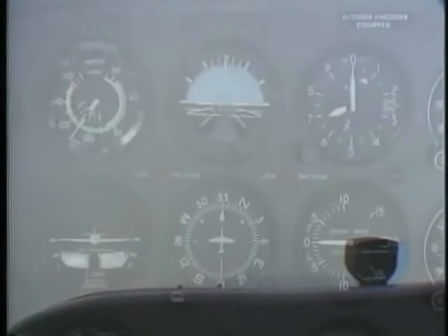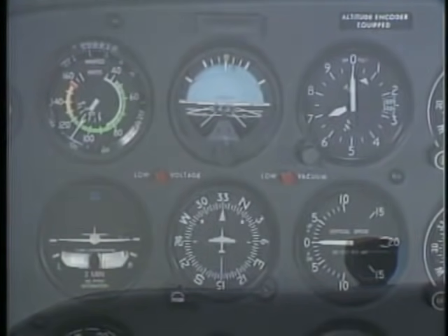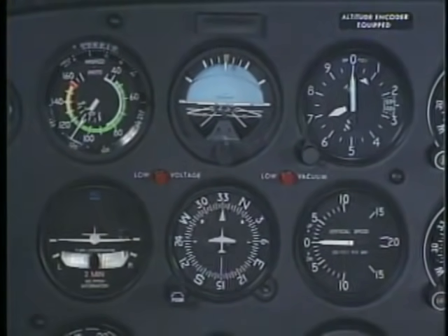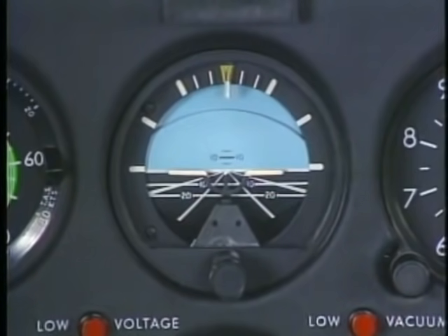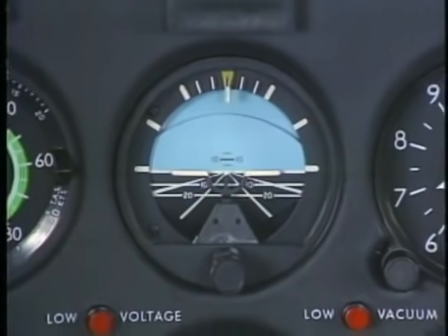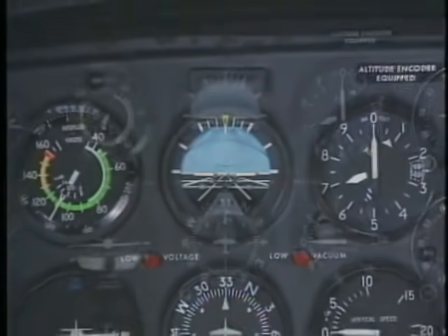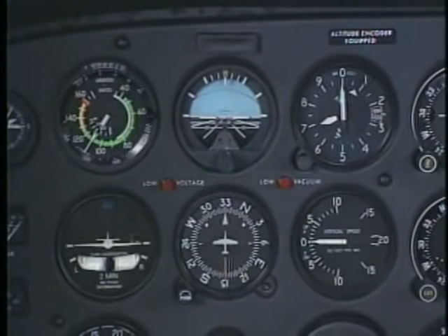Attitude instrument flying is the technique of controlling your airplane by using the flight instruments rather than outside visual references. It involves establishing a precise attitude for a given power setting and then maintaining that attitude by reference to the flight instruments. When a change in the airplane's attitude is required, initially make the change by referring to the attitude indicator. Then scan the other instruments as needed for verification.